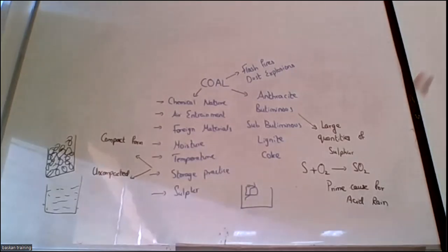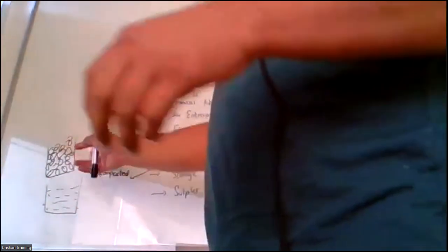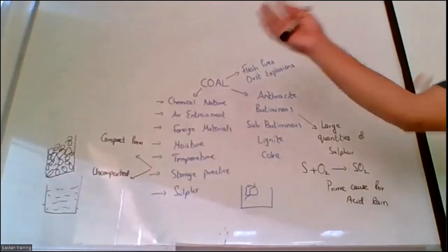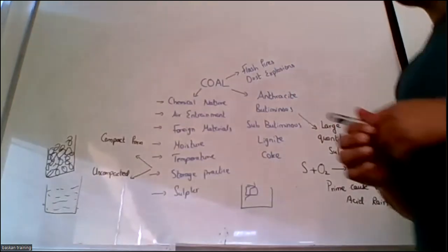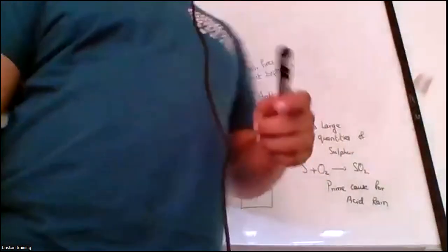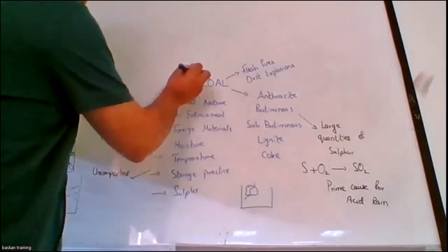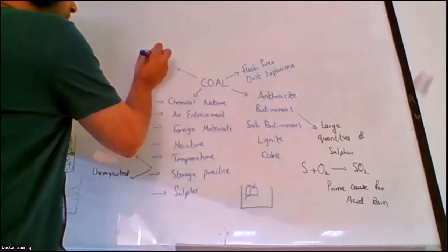Okay, it may take up to 6 to 7 days with the most effective agents. But the important thing here is that whenever the coal is stored, as we have discussed, it's usually in silos. Okay, so tanks, big container silos. So let's say I want to provide extinguishment, or firefighting, for coal. What agents can I use on a coal fire?